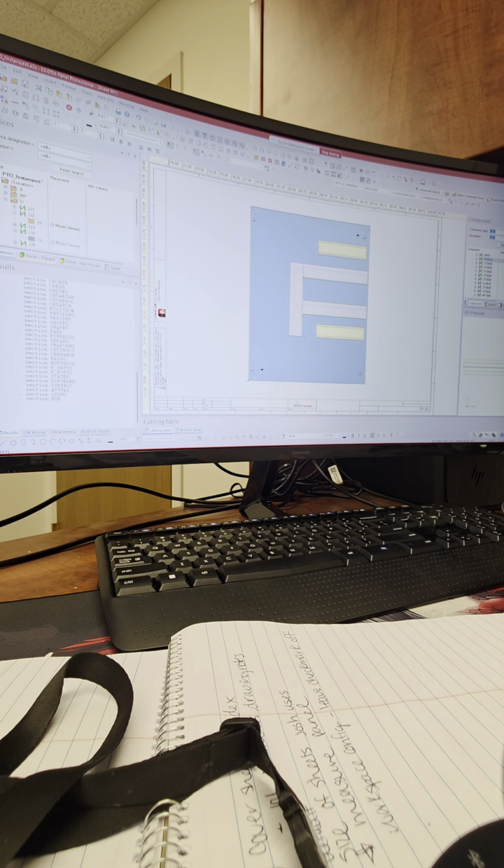Can we go through the folder thing again? How to organize them, just real quick? Sure. Okay. So we made this. We made the MP. Okay, so let's just move these items where it actually should be, considering that's the thing about dynamic parts. When you bring in a dynamic part and you don't choose location at the very beginning, they just go in this automatic folder. So for right now, let's just collapse U2 and U4 for time being. Looks like we missed the U4 on the selection. Right click on U4, just to ungray it out. Click device properties.